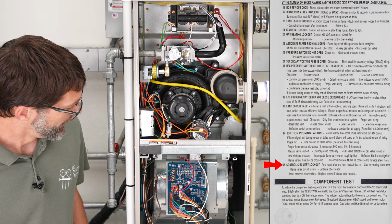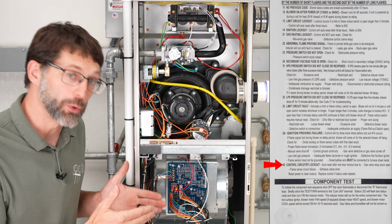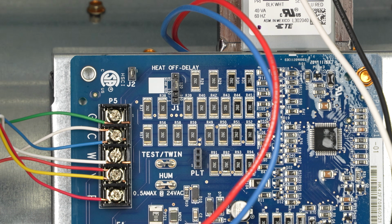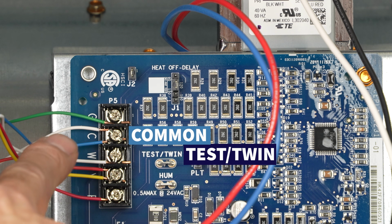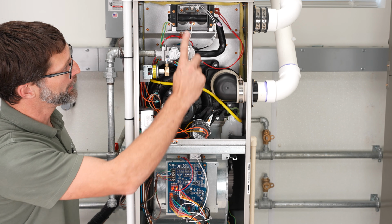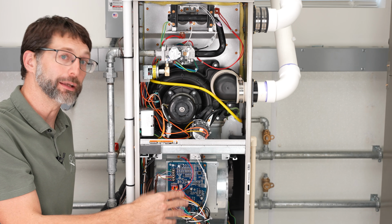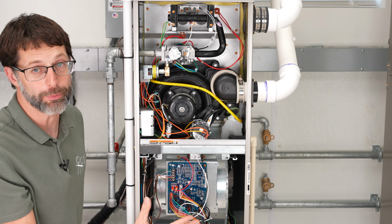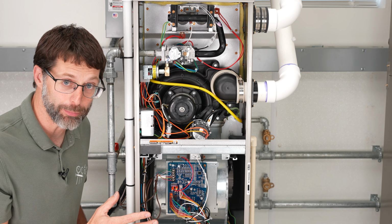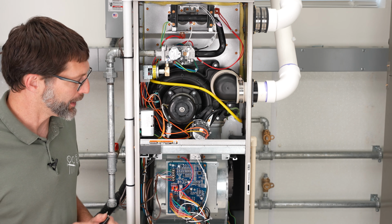And so next, I just wanted to cover how to do a component test. Now, a component test is a pretty simple procedure, and that can be done down here on the test twin and the common. But basically what's going to happen here is the inducer motor is going to turn on, the hot surface igniter is going to turn cherry red, the blower motor is going to turn on at its lower fan speed in heat mode, and then also in cooling fan speed. So it's going to test out those 4 items, and it's going to do it for 15 seconds apiece. And so we typically are not doing this test that much out in the field, but I just wanted to show you how to do it.